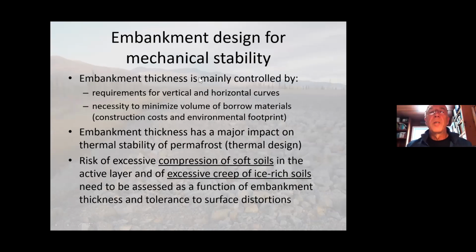Okay, we'll come back to some techniques to do that, but I just want to say a few words about mechanical stability. Of course, the design of an embankment is first of all controlled by requirements for vertical and horizontal curves. There are design requirements that you can allow for, for vertical and horizontal curves, and that will dictate the amount of fill that you need to put in a given area. Of course, this is also done by trying to minimize the volume of borrow, so whatever is excavated is used in the fill section. This is important for cost and environmental footprint.